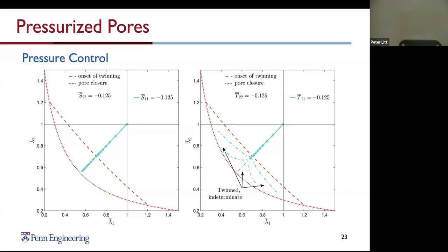And so if you apply hydrostatic pressure to a fluid, the shear deformation is indeterminate from that because there's zero shear modulus. And so once you get into this regime, you could go in any direction down that path. According to the energy, there's no preferred direction for you to travel. So there's a difference based on if you apply Piola-Kirchhoff type tractions or Cauchy type tractions.